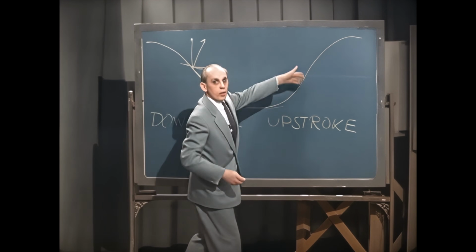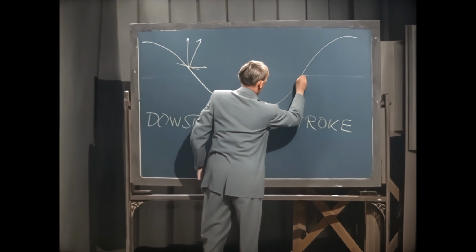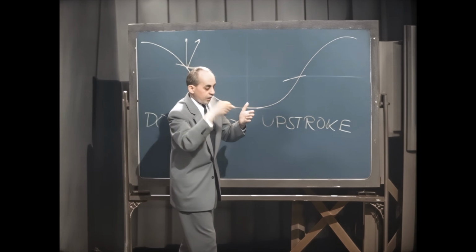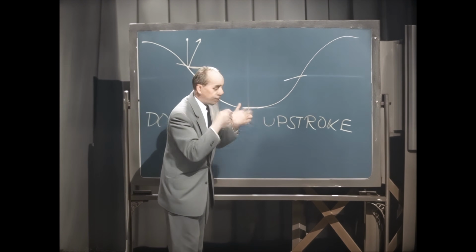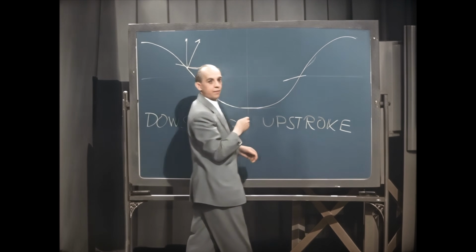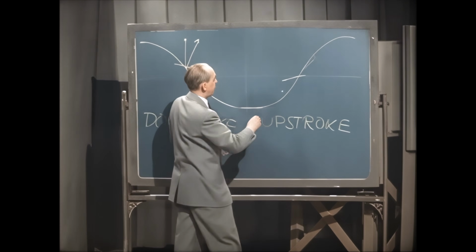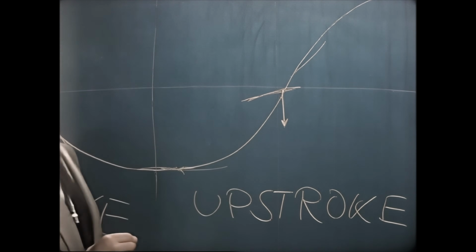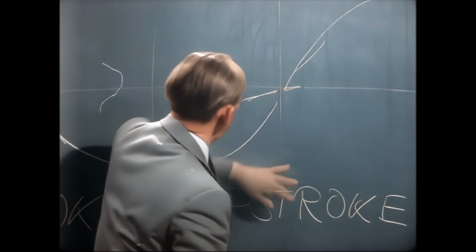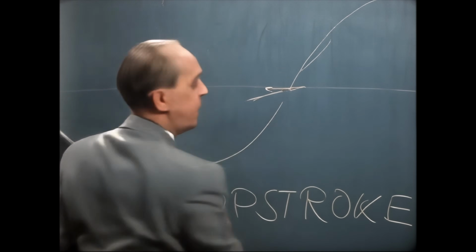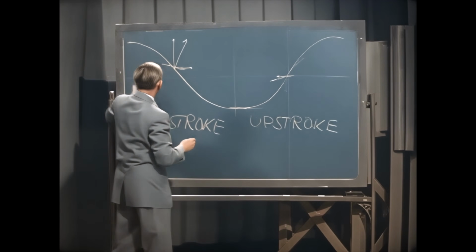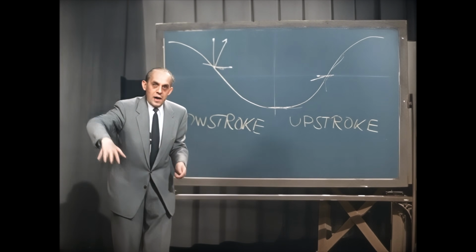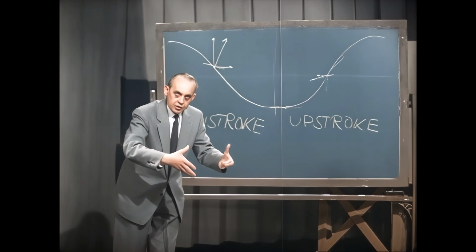Now when we pull it up, then in this position the wind which the wing feels comes from above, and we have actually on such a model a little down lift, or practically no lift at all and only a small drag, so that during the downstroke we produce high lift and forward thrust.